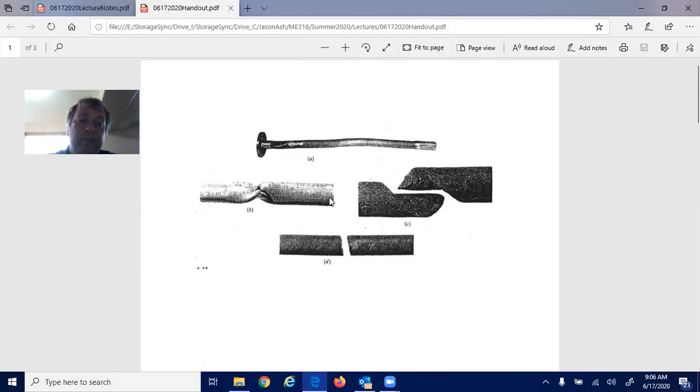And if you were just to remove that inner half, you would decrease the cross-sectional area by 25%, and that would only increase the shear stress by about 6 to 7% on that outer surface if you reduce that. So J really increases as you get the material further away from that center of the cross-section.